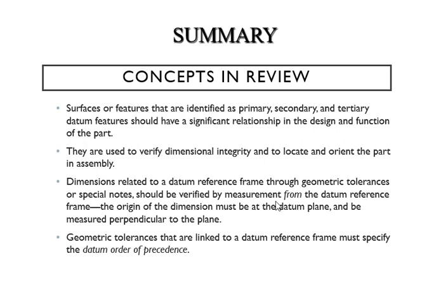Again, order. If you use more than one datum feature, then you have to follow the order. The order depends on the functional design. Your left is more significant, all the way to your right. So primary is more significant than the secondary and tertiary.